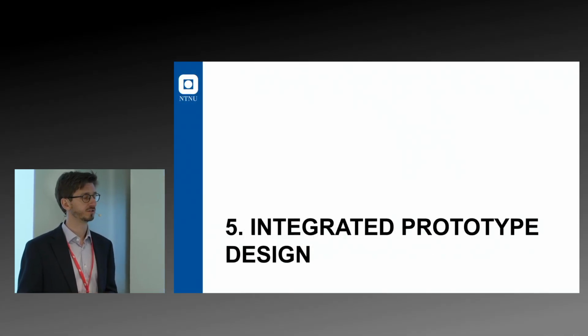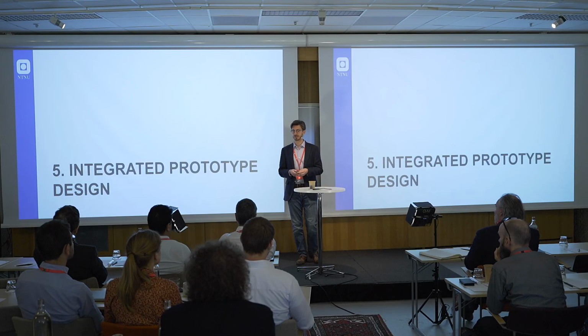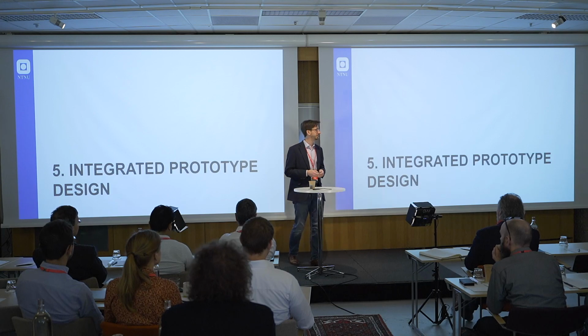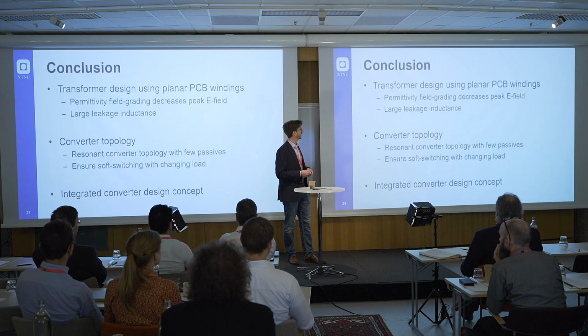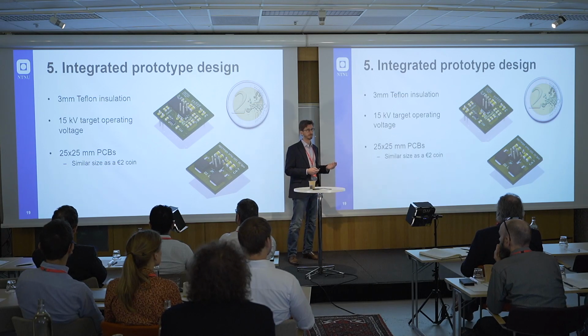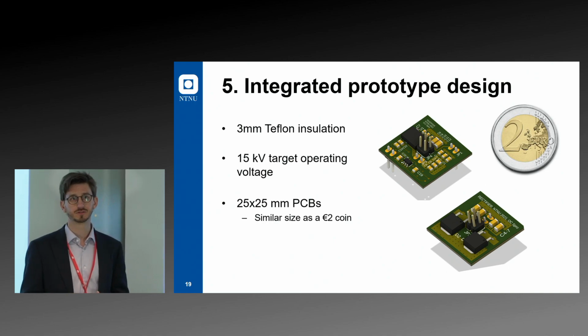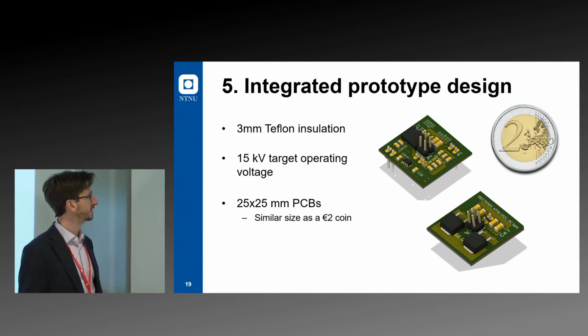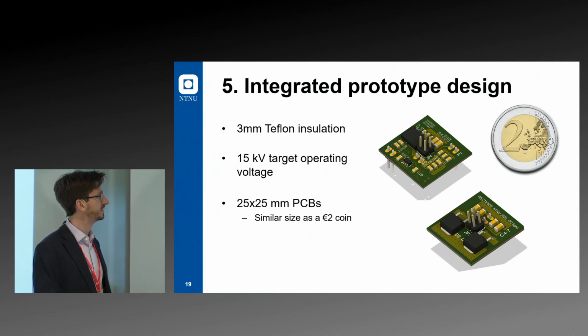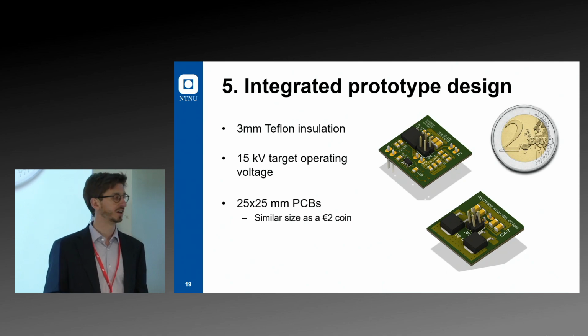After the PhD, I continued this work a little bit to look at what the integrated prototype could look like. So I'll just give a brief overview of that. We redesigned it with 3 millimeter insulation, targeting a 15 kilovolt RMS operating voltage. So we'll have the primary side, the PCB. Here we have the gate driver chip, making it a very, very compact solution because all the electronics are inside, and the rectifier.